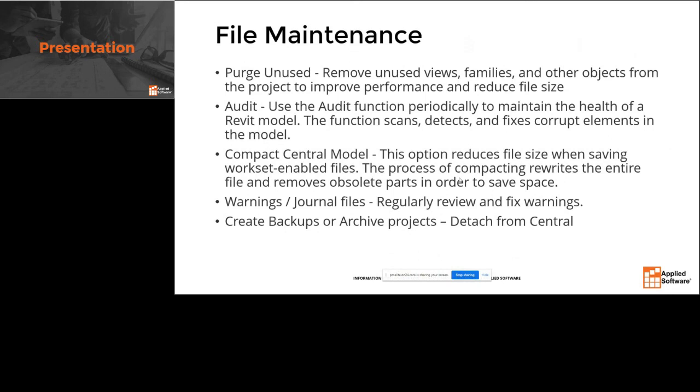And I always get asked, what does it do? It basically fixes corrupted elements in the model. If there have been bad families, the families, some of them, when you have multiple types, can go corrupt. It just really depends on the way the family was created. Like we have valves and pipe families that have been around since like 2015.